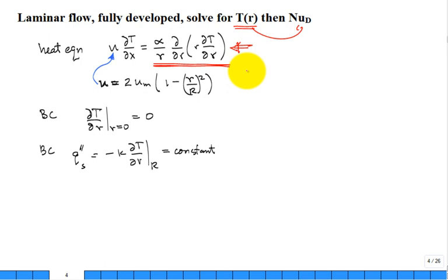It looks like that spread of heat due to diffusion. It's a diffusion transfer of heat. Fourier's law is in there. If I put in a k right in here, thermal conductivity, that's going to come from that alpha. Remember, alpha is k divided by rho C. That's where that alpha came from. They took the k out from inside.